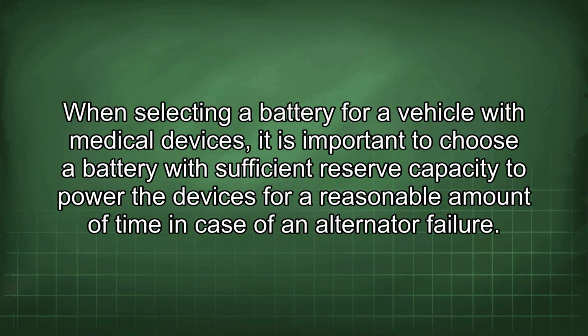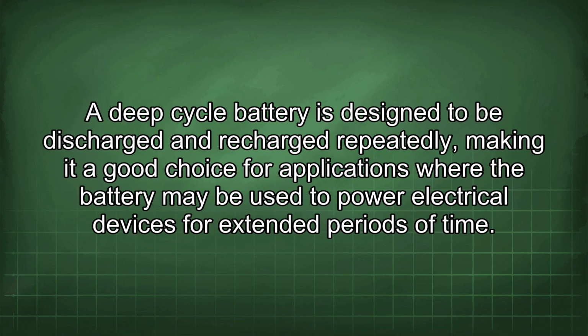When selecting a battery for a vehicle with medical devices, it is important to choose a battery with sufficient reserve capacity to power the devices for a reasonable amount of time in case of an alternator failure. A deep cycle battery is designed to be discharged and recharged repeatedly, making it a good choice for applications where the battery may be used to power electrical devices for extended periods of time.